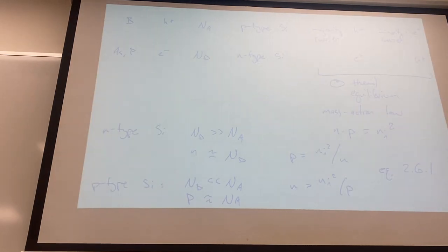So that's accounting, and we're going to switch gears to mobility next. So is at least the jargon and terminology all kind of grokking? We'll care more about minority carriers later, because it turns out if we exhaust all of this, we find a way to get rid of all of them, that can impact the behavior of more advanced devices. But for now, we're just trying to get a handle on what is in the semiconductor, how are we changing silicon, and how do we describe those changes? We have kind of magically added a bunch of other material, other atoms, into the silicon lattice. What happens? What does it look like?